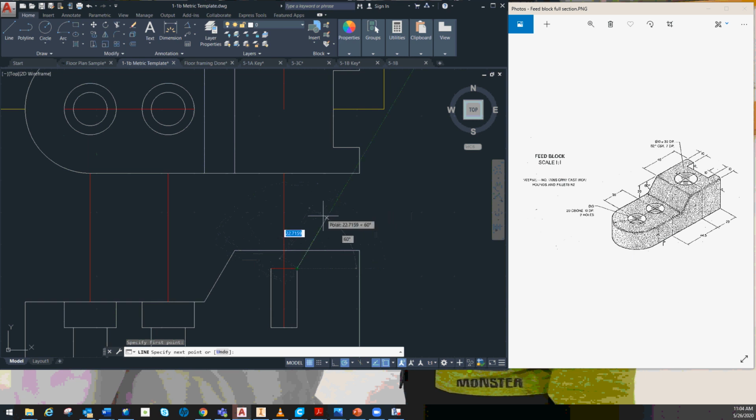So in order to get the angle number that this line is going to be drawn off of this corner, we have to realize that it's 82 degrees total. So that means it's going to be 41 degrees from a vertical line in one direction and 41 degrees from a vertical line in the other direction. So then those two partial angles will add up to give us 82 degrees. So we're going to want to now go 90 degrees minus half of our countersink angle. So we're going to go 90 minus 41, which gives us 49 degrees.